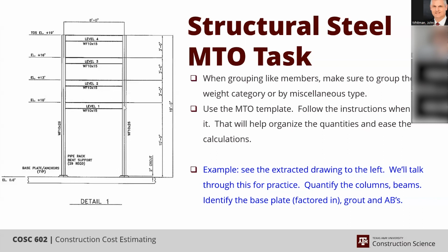The connection allowances for light and extra light are around 12%. By the time you get to heavy and extra heavy, you're down to around 4%, because most of your connections are made of medium and lighter heavy steel members, so the ratio decreases as your steel members increase in weight.